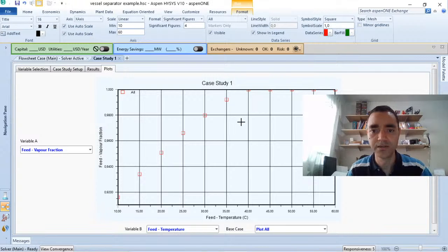Or, for instance, if I'm talking about a rotating compressor and I'm sending gas to the compressor, I cannot have liquid, and if I have liquid, I can break equipment that costs $2 million. So this is the way that we do plant design in real life.